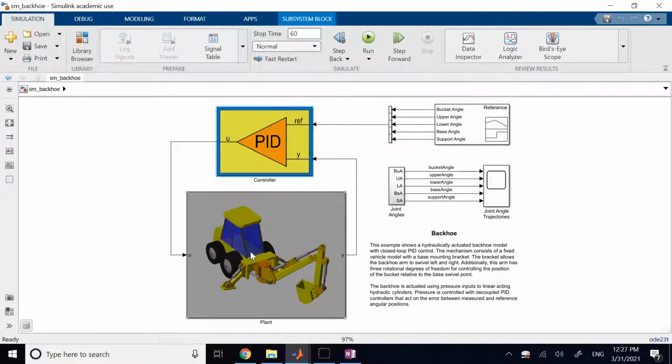Okay, so if you want to design a controller for a complicated system, a drone, a hydraulic system, anything complicated, you can design them in CAD, export them into Simscape, and then in Simscape and Simulink you can add a lot more stuff, right? You can use different toolboxes that we have, like the control toolbox, design a controller for them and investigate the behavior of them. You can even compile them into hardware. I'll show you in a second, and so many other things. So by combining MATLAB and SolidWorks, you can do very complicated projects.